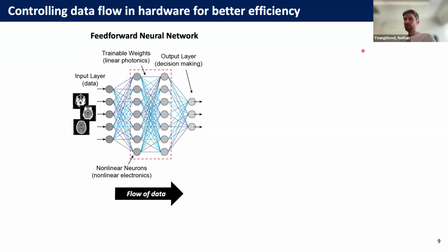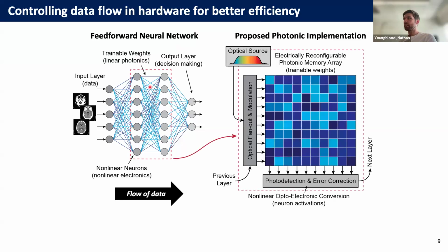Okay, so now that we have memory cells, and that was just one example of many in the literature that people have been working with to switch these materials back and forth electrically and optically and use them as memory cells, we want to put them in a neural network. So if we look at a neural network, we've got an input vector that we can multiply by a connectivity matrix. And this connectivity matrix can be encoded in some sort of two-dimensional array of these memory cells. So if we were able to map this neural network onto a memory array, we could think of actually implementing a fully connected feed-forward neural network where information passes from the left to the right without needing to load information into these memory cells.